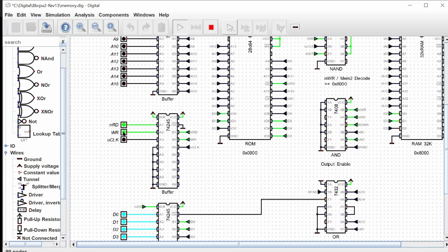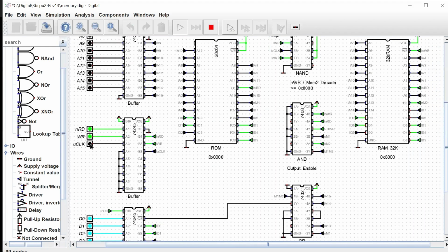So the write signal is being raised. The data bus signals are already going to be stabilized, and our clock signal is going to occur here, and our RAM chip is going to clock in the stabilized signals from our data bus. So that's going to be our fix, and it's not quite as eloquent, I think, as what I was attempting to do before, but in a nutshell, I was using the wrong signal.